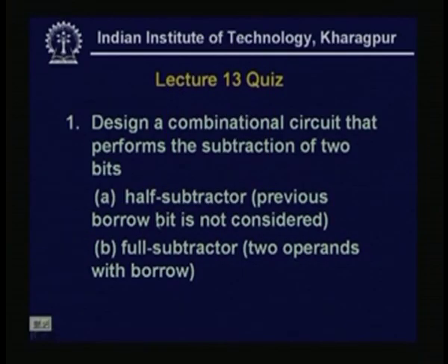Half subtractor means a single bit subtraction where the previous borrow bit is not considered. For addition it was the carry bit and now it is a borrow bit. For full subtractor, the two operands as well as the borrow bit from the previous subtraction should be considered. So, these are the quiz questions for this current lecture. Okay, thank you.